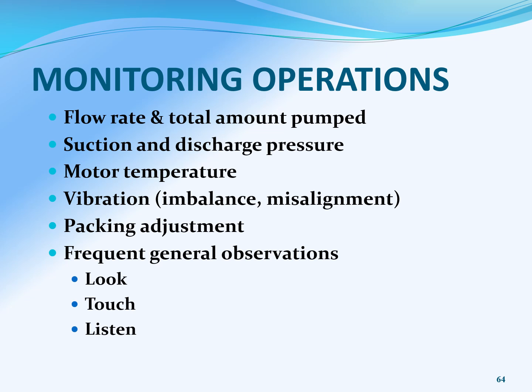So, just to touch on what we were discussing in the last lecture real quick, we talked about flow rates, suction, discharge, vibrations, packing, how to do a general inspection of your pump. You want to look at it, you want to touch it, like I said, with the back of your hand, don't touch it with the palm of your hand. And then you want to listen for any kind of abnormalities. As you progress in your water industry careers, if you're out inspecting pumps, you'll learn to identify anything that's abnormal after you've inspected a few of them. So let's get going into the rest of this.